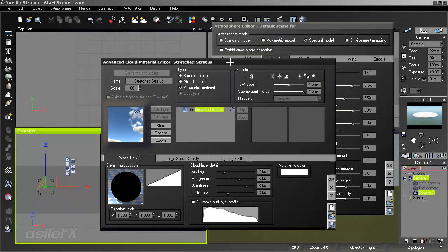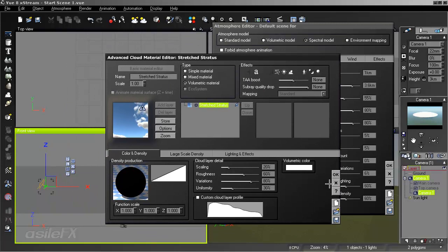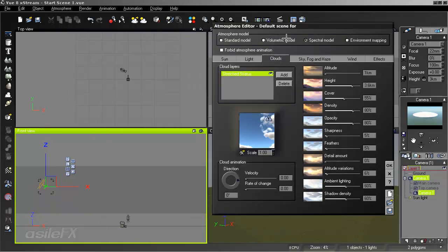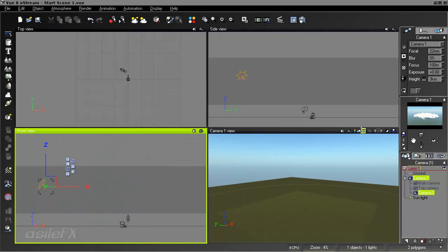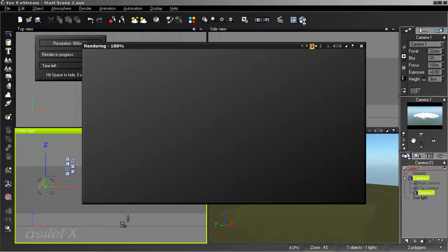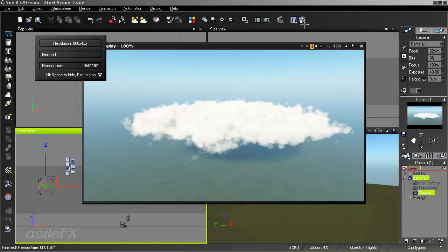Go ahead and close that out. But I do want to show you exactly what happens when we start to bring in a little bit of detail. So let's take the detail amount and set it to 25, which is going to be 25%. And what we're going to start to see is a subtraction around that noise. So here we can see the render and that circle having the edges removed by the detail function, which is an internal function that can only be edited by the sliders that are shown.